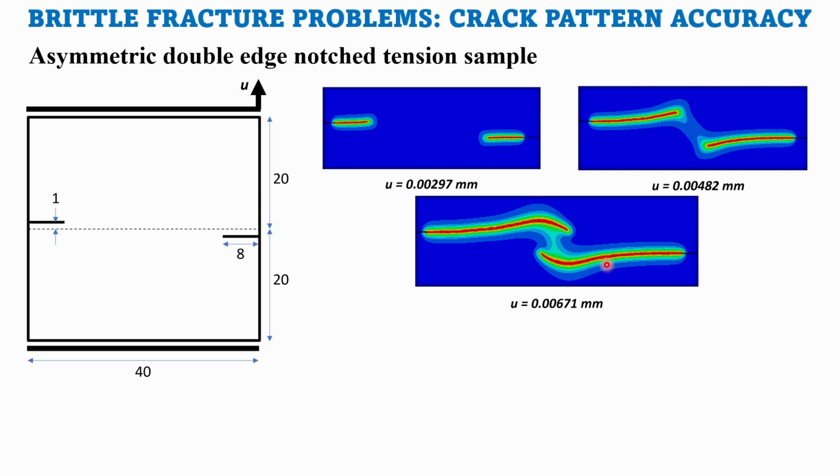Okay, but there are also different patterns that you can observe in this problem. If your loading rate, your displacement, is very high, you will see that these cracks initially meet. So from this stage they will form an S. They will eventually meet. They will not go over one another. But if your loading rate is lower or if your displacement is lower, only then you will be able to see this pattern. Try it out for yourselves. You will be surprised.